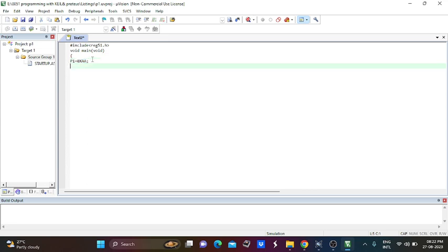At the same time, again you can type P1 is equal to 0x55. So now the alternate toggling takes place here. The 55 value is 0101, and again the lower nibble 5 value is 0101. So totally 8-bit values are assigned in port 1. The first value is 1010 1010, and again 01010101. So totally 8 bits of values are assigned in port 1 separately for alternate toggling continuously. So I just close this program, and that's all about our program.